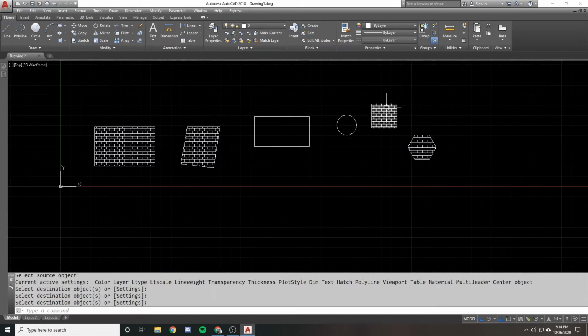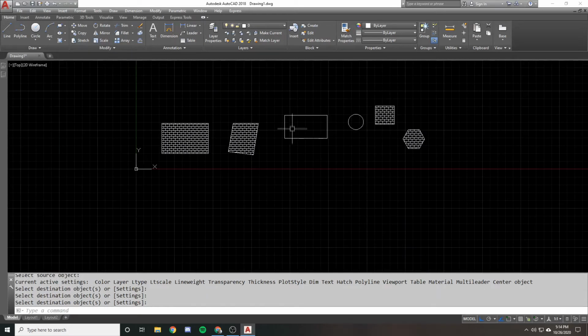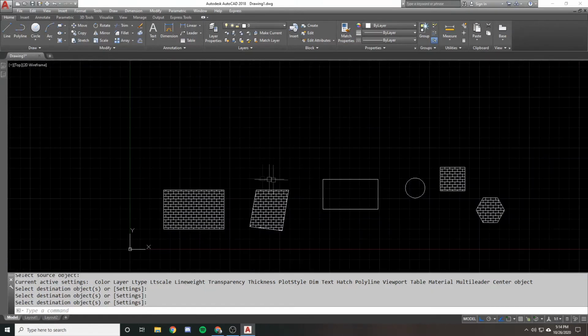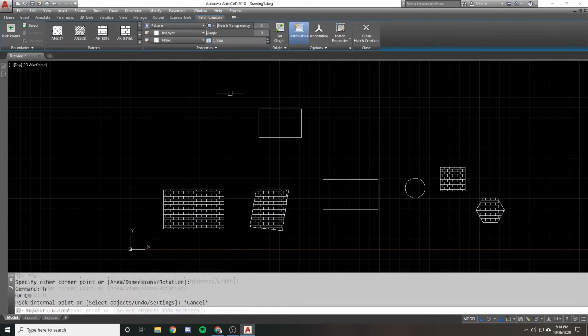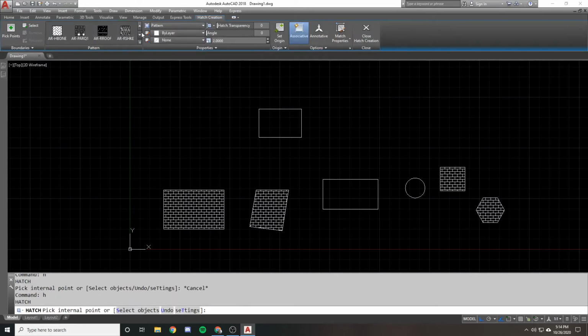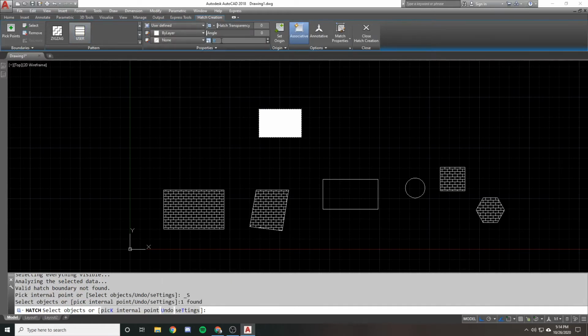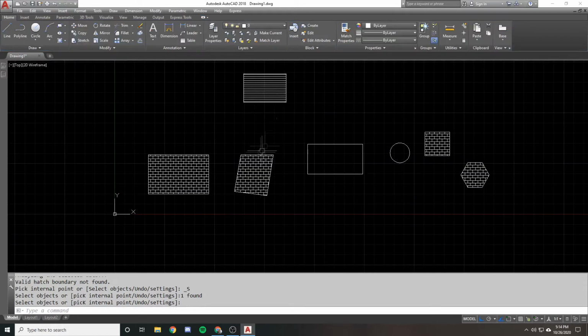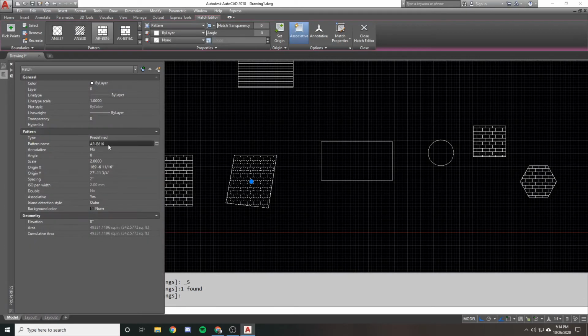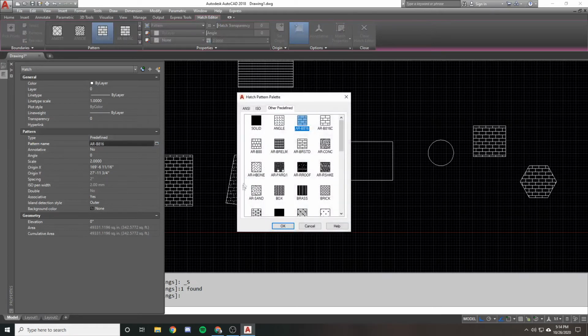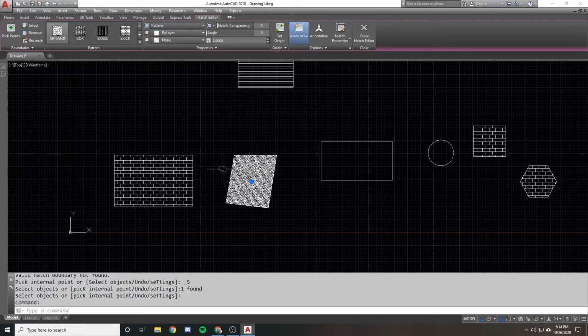So matching hatches is actually kind of nice, because let's say you've got a couple different patterns, like let's say I have another one over here, and this one's a user defined, all the way at the bottom. See, it's so far though. So I've got a user defined, and I do select. Oops, I meant to do a select. Okay, and then we're gonna do 12 inches, and we'll leave it like that. Okay, done. And let's say this is just a different pattern altogether. Sand. Okay.